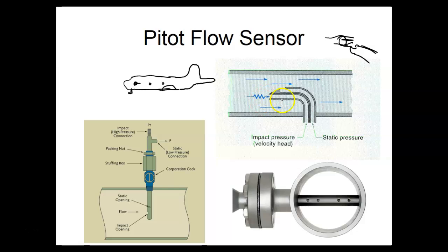So ours, we bring in pressure, then we compare that to a static pressure. What was nice is that this made it work even at higher altitudes, because when you went up, your static pressure would go down and your pitot pressure would go down, but the difference would still be an indication of how fast the plane was going, which was basically a flow indicator, you know, how fast the air's flowing over the plane.